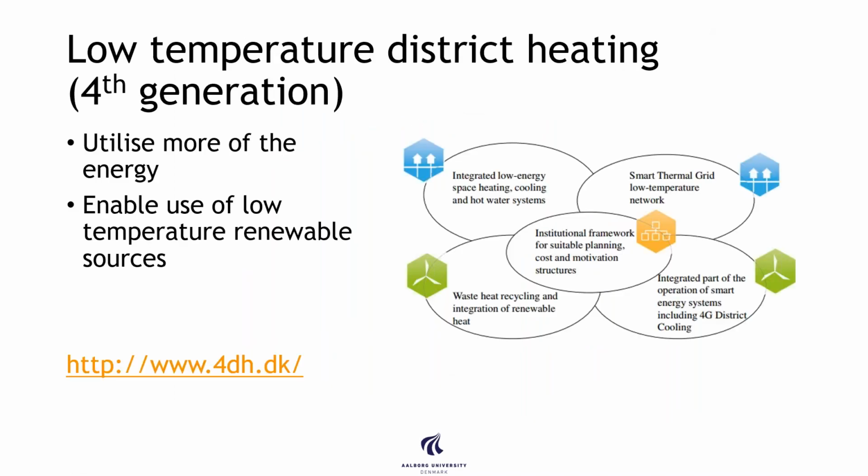So why do we want to go to this low temperature fourth generation district heating? We also investigated that in a research project called 4DH, and you can access it on the website here. We want to utilize more of the energy that is in our waste heat sources and our renewable energy, and we do this by enabling the use of low temperature renewable sources.